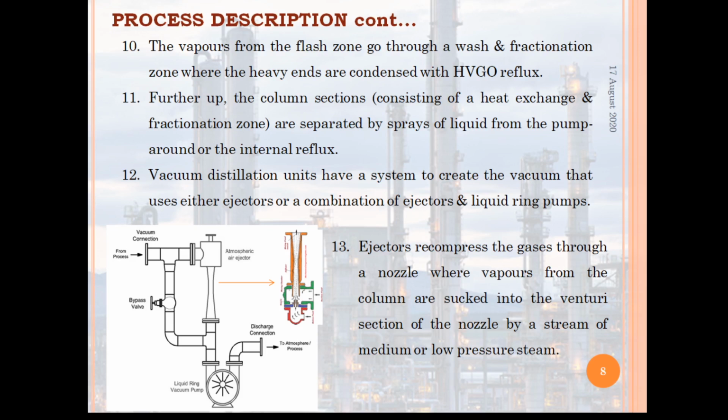And further up the column, these sections, consisting of heat exchange and the fractionation zone, are separated by sprays of liquid from the pump around or the internal reflux.